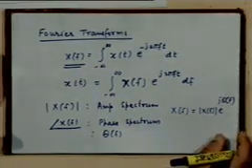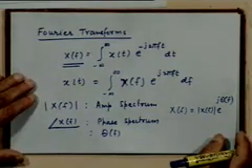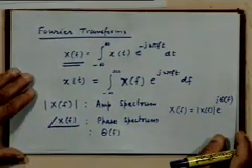Now there are certain conditions which the signal x of t must satisfy in order that the Fourier transform exists. Right? I will simply name the conditions. These are called the Dirichlet conditions. There are 3 of them in number. The most important of these 3 conditions is the requirement that the signal be of finite energy. Right? That is, it is square integrable. There should be a magnitude square integrable function of time. Right? So please review these conditions yourself.